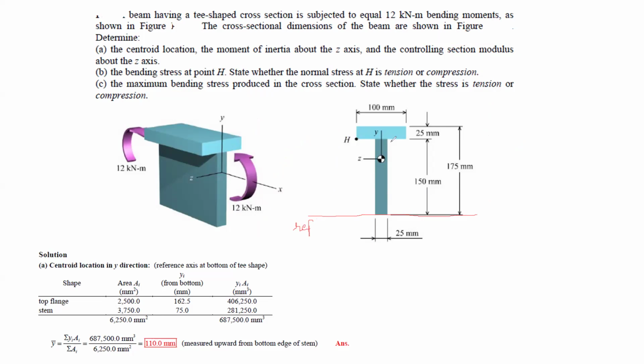And then we look at this composite structure and divide it into the possible number of areas, right? For example, this is one rectangle, I call this area 1. And then I have this second rectangle, I call this area 2. Now, what I need to do is develop this equality. If I'm talking about area 1, rectangle 1, then centroid times area, I can write it like this for area 1, plus centroid times area for area 2. If I take this as a product of centroid and area for the individual areas, then it should be equal to the total area,